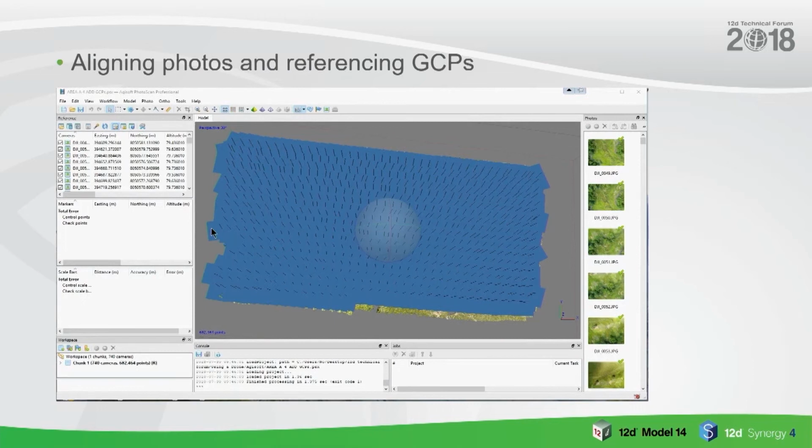Okay, right, so the next thing we do is the coordinates. Actually, there's a slight step between those two slides you probably didn't see, mainly because I didn't put it in. The photos themselves are in latitude, longitude and height, and what we do is convert them to MGA coordinates, the local coordinates. The main reason for that is that when I surveyed those points, I had MGA coordinates for them, and I wanted to be able to import them into the actual job to be able to manipulate the images.